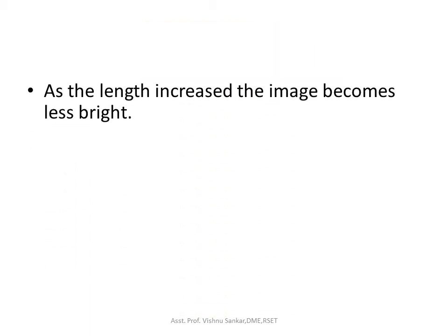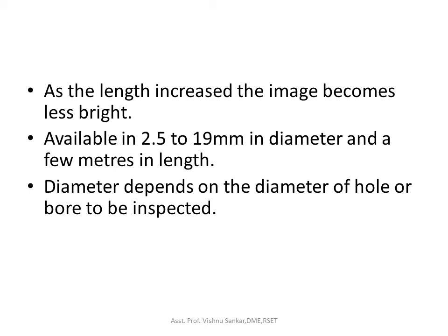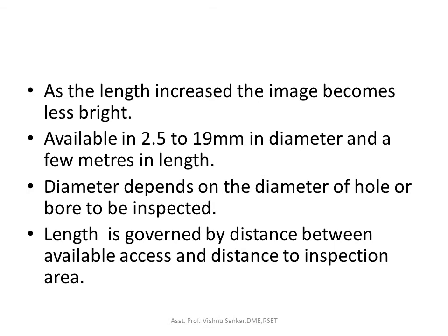In the case of a Boroscope or Borescope, as the length is increased, the image becomes less bright. It is available in 2.5 to 19 mm in diameter and a few meters in length. Diameter depends on the diameter of the hole or bore to be inspected. The length is governed by the distance between available axes and the distance to the inspection area.